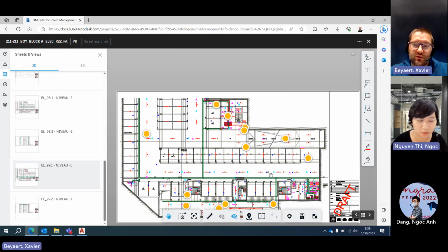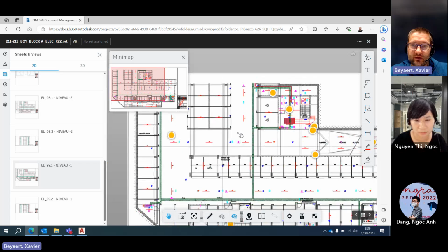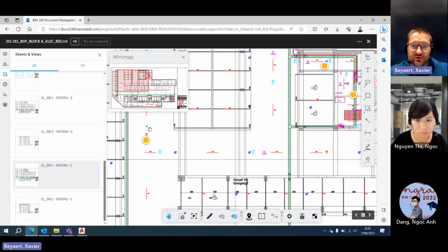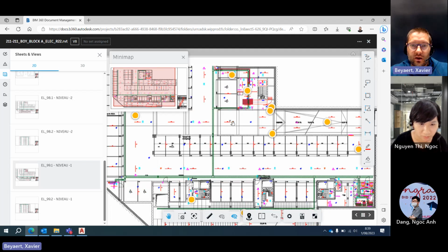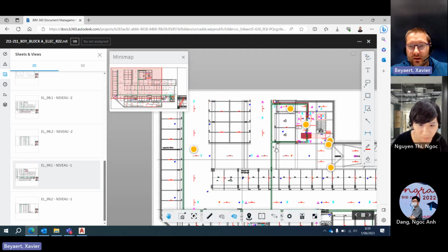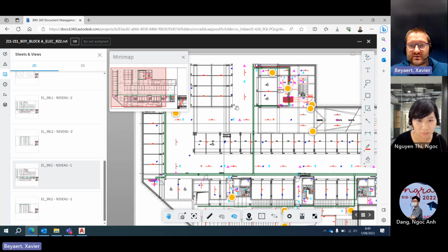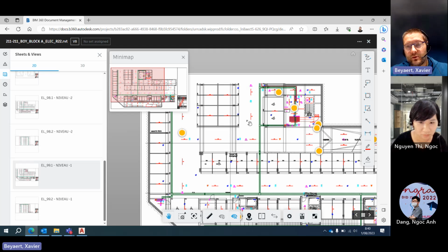What we will do for the control of the lighting, I mentioned we will also add two sensors here. So when the car drives in and goes that way, the lights go on on this side. But we will use DALI, so we can say we put that light at 10%, so it's not dark, but you don't have a lower value of light. And if you drive in that section, it goes to 100%. So that's the idea behind it.